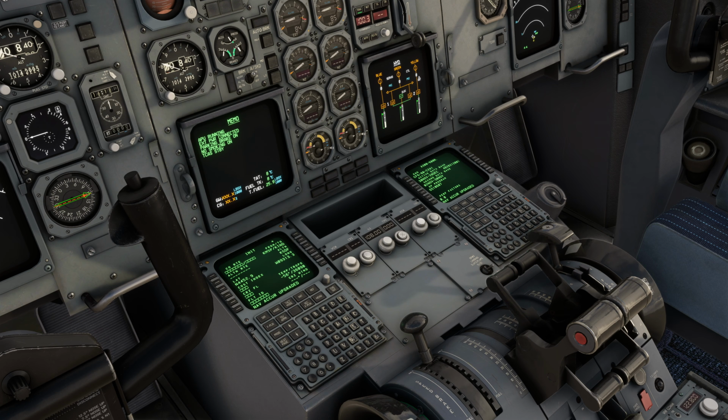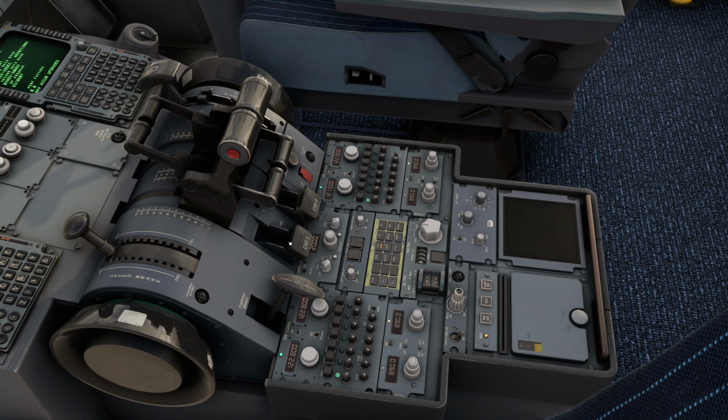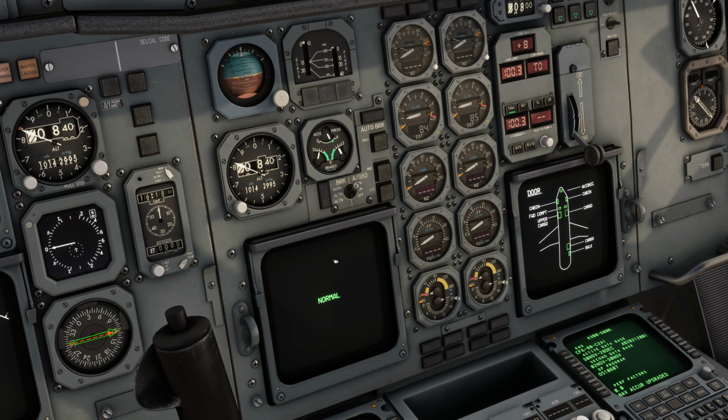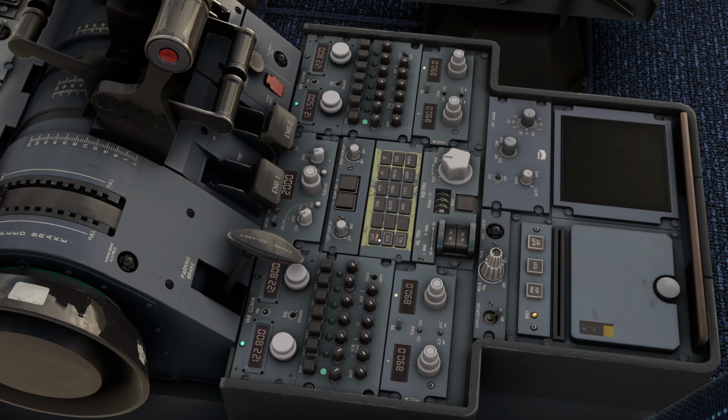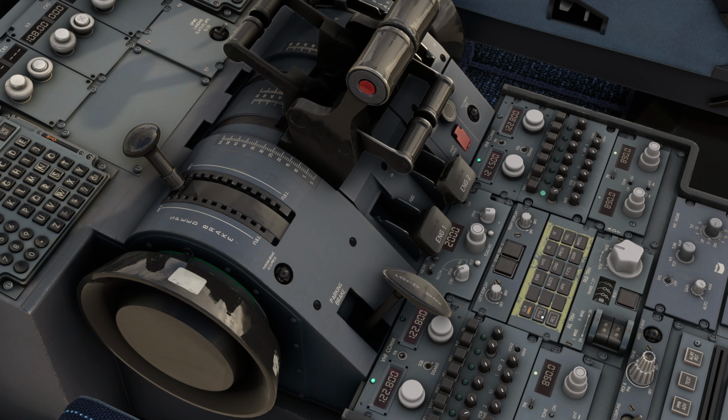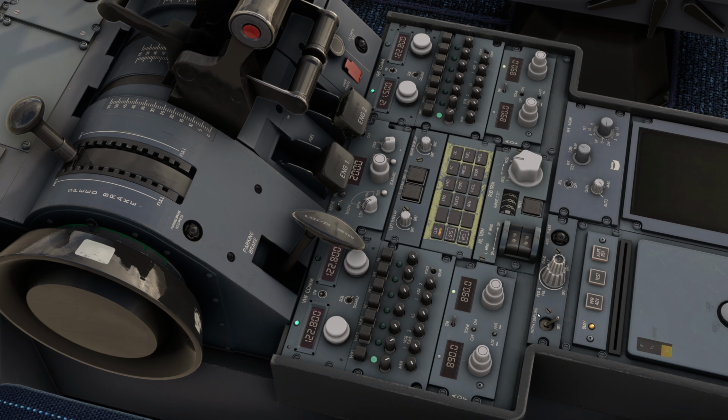sides. Okay then. Going further down, the fuel switches are off. Then we can move down to our ECAM control. We can press the recall. Everything's showing normal, very good. Then we can clear out anything there might be. And that is it.